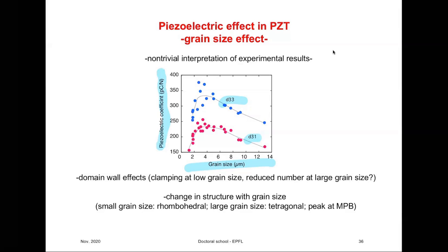At higher temperatures and for a longer time, lead easily evaporates. Once you put the ceramic at room temperature, oxides are very stable, and lead is not going to get out. But at high temperatures, you prepare these ceramics at temperatures between 900 and 1200 degrees. And I think you all know what sintering is. So this is a sintering temperature.